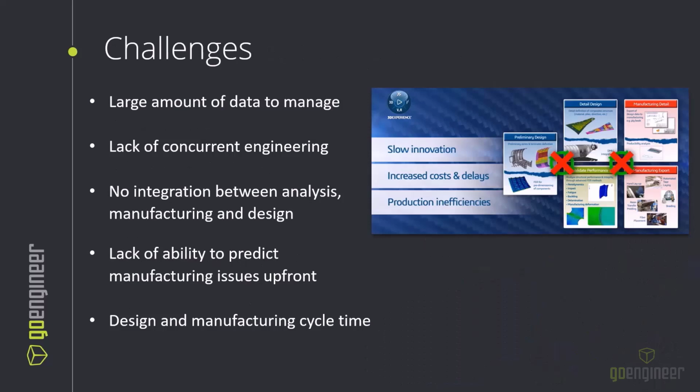And some of the challenges that come with designing composites, specifically when they deal with designing in CAD, and how CATIA combats those challenges are, the first being there's a large amount of data to manage. So when compared to parts being built by solid design or surface design, there's a lot more that goes into it. So to start off, we already start with a surface as our base geometry to develop our composite definition off of. And within that composite definition, we're developing a ply, which is a sheet of composite material. And in that ply, we're defining the contour of that ply, the material associated with it, as well as the fiber direction. And then we repeat the process and define the stacking of those plies and how they stack on top of one another, known as sequences. We also have to deal with how the different sequences interact with one another and how we transition from one sequence to another.